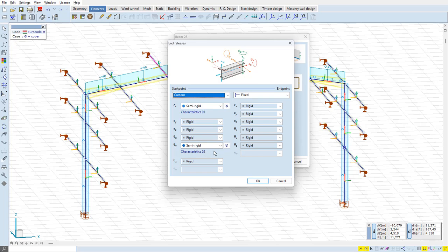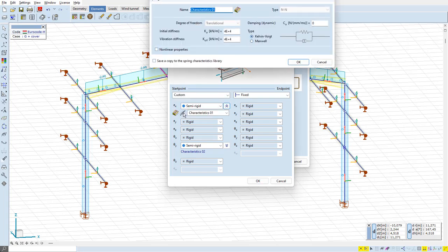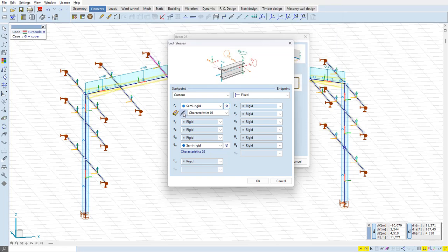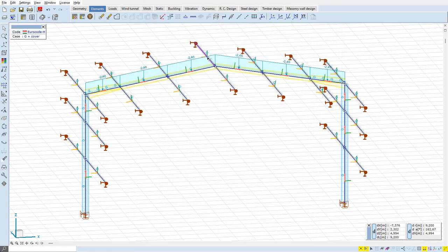This gives stiffness against twisting to the rafter. These have different manually set characteristics. For the AX component, 40,000 kN per meter is set, for example. The last element connects hinged.